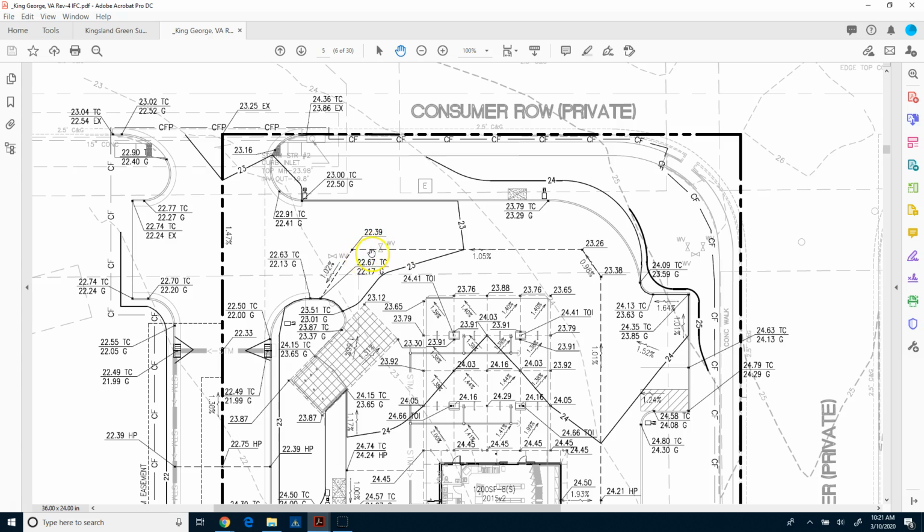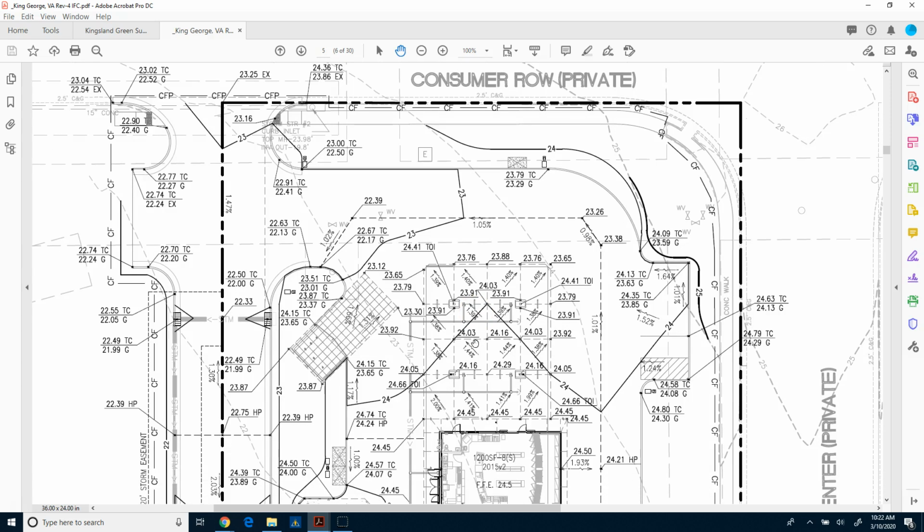And as you come around, you can also see some other key elevations. So these are some elevation points and some slopes that would be used to build the surface model, in this case for grading and/or paving. So if this case was concrete paving, then you would be able to lay out the forms using the elevation that you see here for these fuel islands. You can also see there's some top of island elevations as well.